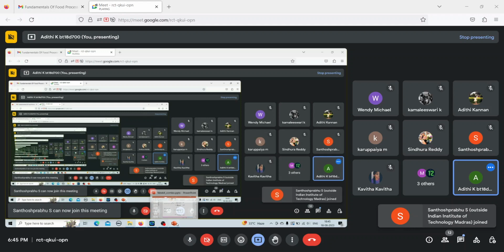So in the case of a multiple effect evaporator, instead of giving steam at each and every effect, you are giving it to only one effect, which means the amount of steam that you give is very, very small. On the other hand, the amount of vapor that you generate is much more. So V by S, V is much greater than S. So the steam economy for a multiple effect evaporator is always greater than that of a single effect evaporator.